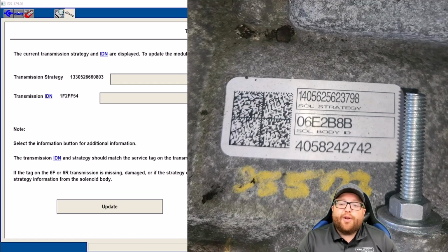So there is one other way you can do this, and what I've done could save you a lot of time. If that junkyard that you ordered the transmission from, say if you're in a small town like me, see if they'll send the PCM with it as well. That way we can take the PCM and pull this information out of it, and we don't have to tear the transmission apart. So that's always a good idea.